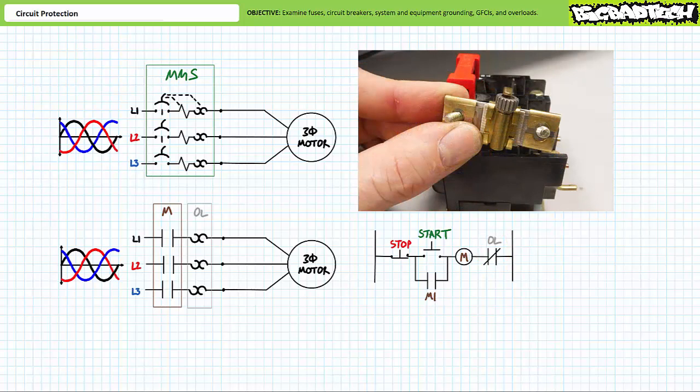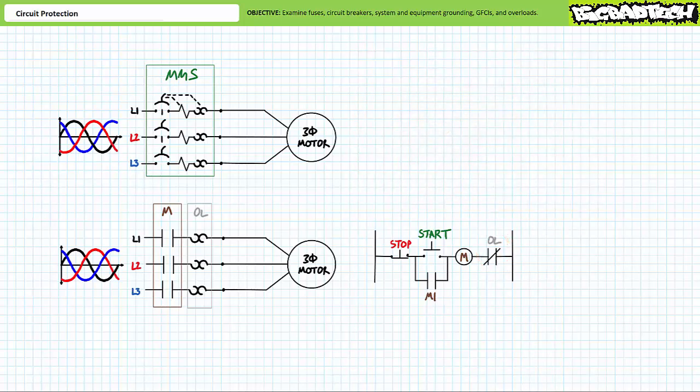A second method uses a metal alloy that passes directly from the solid state to the liquid state at a certain temperature, without the malleable lumpy intermediary. The solid state retains a spring-loaded switch, but when it enters the liquid state, it lets the spring move, and this switch is what again signals the control system to open the contactor. The third overload detection method uses digital means, think a really small computer, to monitor current and signal the control system in the event of sustained high current.